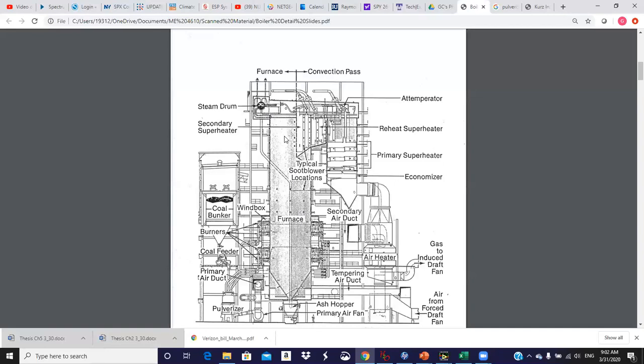circulation. If it is a forced draft boiler, it'll also have a pump, a boiler recirculating pump that will be pushing the water along this path. If it's a natural circulation boiler, it's all done with density gradients. I mean, there's a density difference one way or the other. It's just whether or not we happen to have a pump to pump through, make the circulation more predictable and